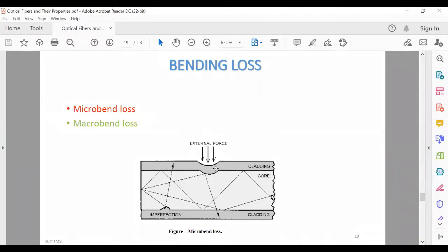To maintain the phase of the light wave, the mode phase velocity must be increased, and when the fiber bend is less than some critical radius, the mode phase velocity must increase to a speed greater than the speed of light. However, it is impossible to exceed the speed of light. This condition causes some of the light within the fiber to be coupled to higher order modes. These higher order modes are then lost or radiated out of the fiber.